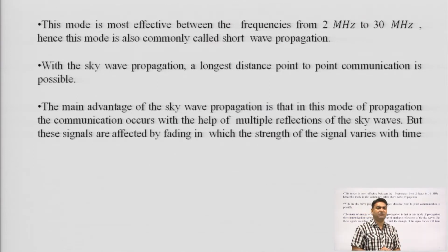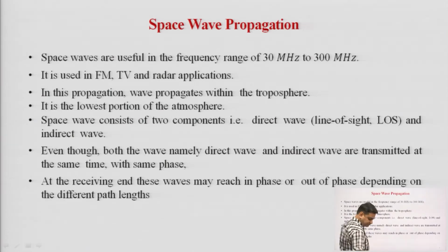The main advantage of the skywave propagation is that in this mode of propagation the communication occurs with the help of multiple reflections of the sky waves, but these signals are affected by fading in which the strength of the signal varies with time. As the longest distance communication is possible, not only one single reflection process, the multiple reflections occur when the distance is too large, means when one particular signal is, suppose this is the